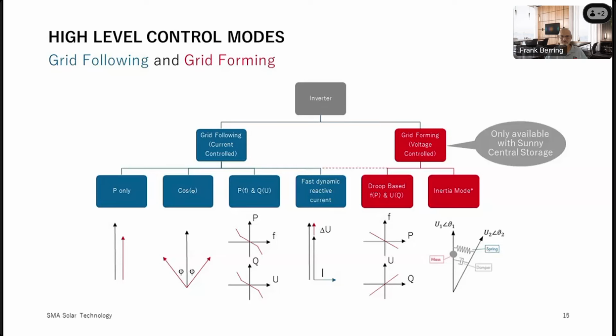So we are injecting reactive current based on fault conditions, and by that means we are operating in a very grid supportive manner. And this is also very fast, as I said. But in order to be as fast as rotating machines are, and we need that for higher penetration of renewables, obviously, there's no way around grid forming, right?